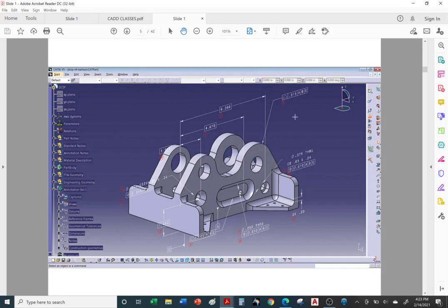Typically, you cut this in half, so it can be 7.5 thousandths taller, or on the heavy side, or on the lighter side. So actually it's 0.0075 on the lighter side or 0.0075 on the heavy side. That's roughly the thickness of a hair, or slightly bigger. The thickness of a hair is about 0.005, 0.004. Okay, so this is GD&T.